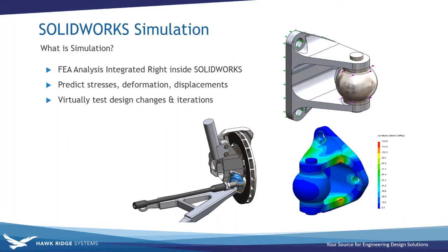As far as SOLIDWORKS Simulation, it is finite element analysis built right into SOLIDWORKS, and it lives on the CAD model, the part or the assembly. Basically you're going to be going in and applying your forces and loads to the model, and it's going to be predicting stresses, displacements, whatever parameter you're interested in from that. And it can be as simple or as complex as you want it to be. SOLIDWORKS Simulation can be used on very small, simple parts, or it can be used on a large assembly. There's no artificial limit to how big the problem can be.